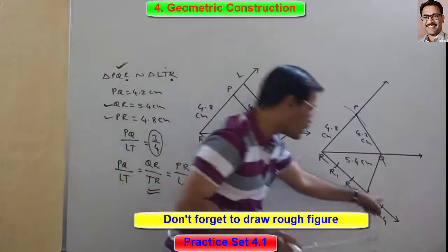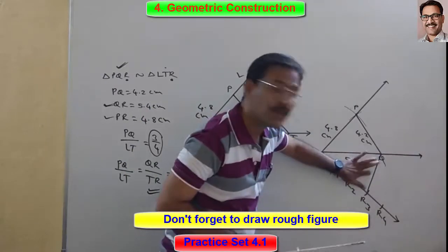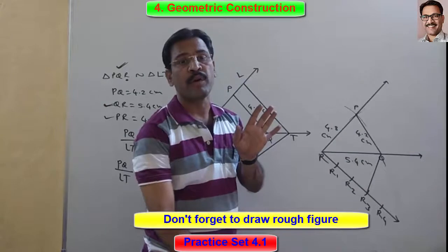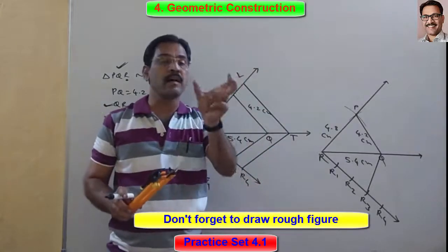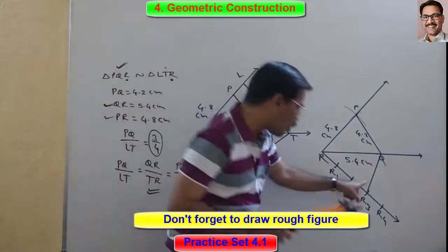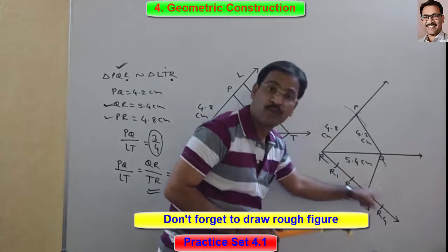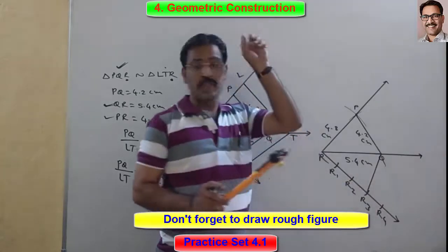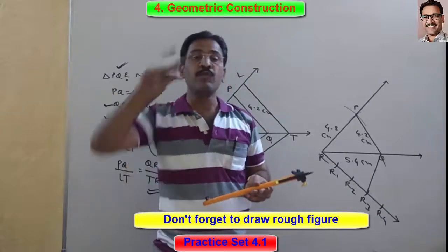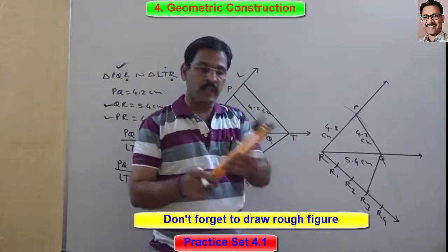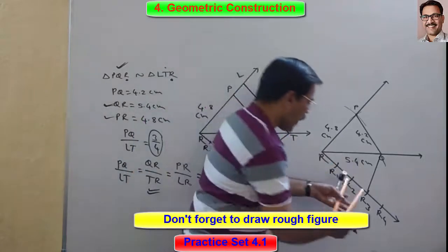Now, the important part is what from R4, we have to draw parallel to this QR3. Now that one is very important. We know in that basic construction how to draw that congruent angle. This is the angle which we have to draw here, the same congruent angle. That procedure, try to remember. If you do not remember, again try to watch that video on how to draw a congruent angle. See, I'll take some distance in the compass, that should be more than R2 and R3.